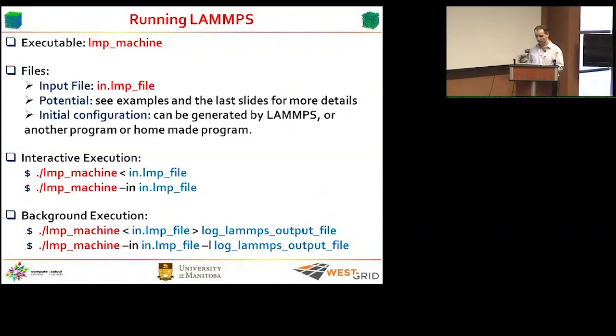and add the input file. There are two ways: I can use the first command or the second. LAMMPS accepts some command line options. For example, to tell the program I want to use this file, use -in and the name of the file. This is an interactive execution.